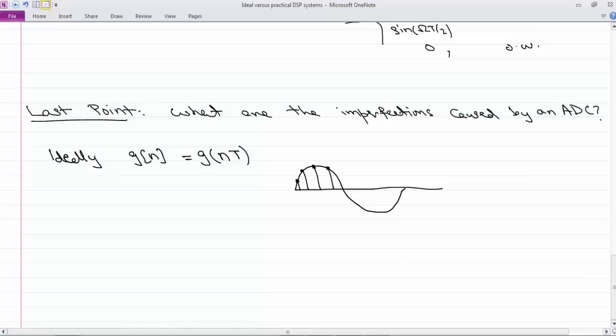If the amplitude of the signal was higher, then you will record higher values, and technically this mathematical formulation doesn't care what the value of Gn is. It just records that value. Now, in practice, these sampling systems are made up of circuits, and they cannot actually record infinite values. So they have a certain range within which they get to record signal values.